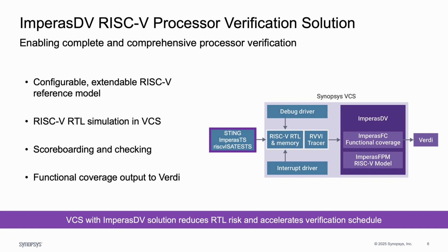This is a bit more detail on the processor verification solution, showing that co-simulation environment within Synopsys VCS, Verdi reporting the functional coverage results, and then Sting, Empirus TS, and the RISC-V ISA compliance tests that are sitting there and driving the environment.